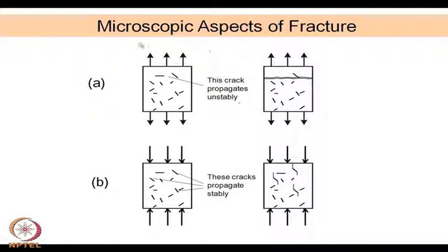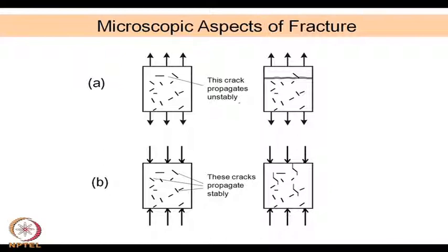Well, these are other microscopic aspects of fracture, both in tensile load and compressive load. We have earlier seen that it is the pre-existing cracks which are primarily responsible for the brittle fracture of ceramic materials. Now, these pre-existing cracks can be generated for various reasons, primarily during preparation, because of the thermal history, and sometimes because of a dual phase material having different thermal expansion coefficients.